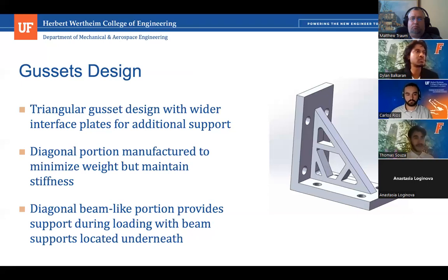I don't have the calculations with me at the moment, but we did look into how much load an appropriately torqued M5 fastener could withstand. And we found that it was able to withstand the majority of the loads, all of the loads that would be applied. And we would just be using Loctite as an added level of security for fastening it down.